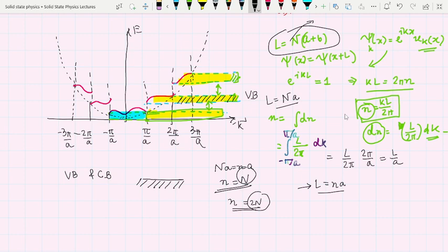And the next succeeding band is known as the conduction band. The basic property of a semiconductor is that the valence band and conduction band are separated by a very small energy gap, which is known as the forbidden energy gap. For silicon it is 1.1 electron volt, and for germanium it is 0.74 electron volt.